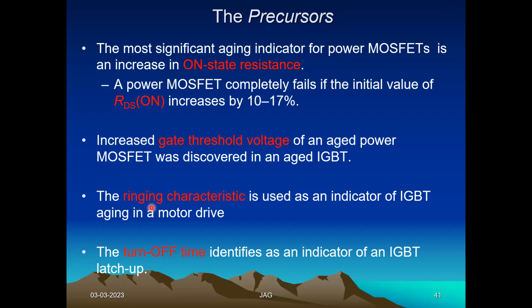Understood? Now you are monitoring the system in real time. From the system, you derive the precursors. This current, real-time precursor, you feed to the developed model. What will happen? The SVM will immediately come out with a positive number or a negative number. If it is a positive number, that will be a healthy case. If it is a negative number, that will be a faulty case.